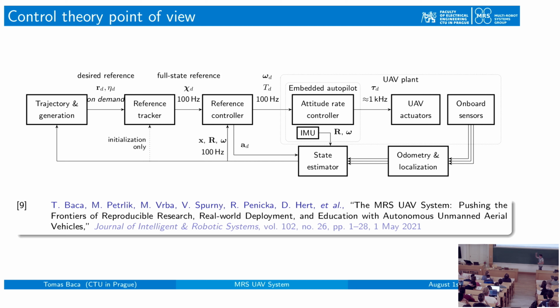and this is the image of the normal drone's control pipeline. You might have seen it in every paper, everywhere. Typically, there is some drone plant, which in our case contains the attitude rate controller on the Pixhawk, and somewhere above there are controllers, reference generators, planners, and so on. These building blocks are typical research food currently. Many groups are developing their own controllers, trackers, planners, mappers. And I'll quickly go through what we have here in our system as those 4 blocks.